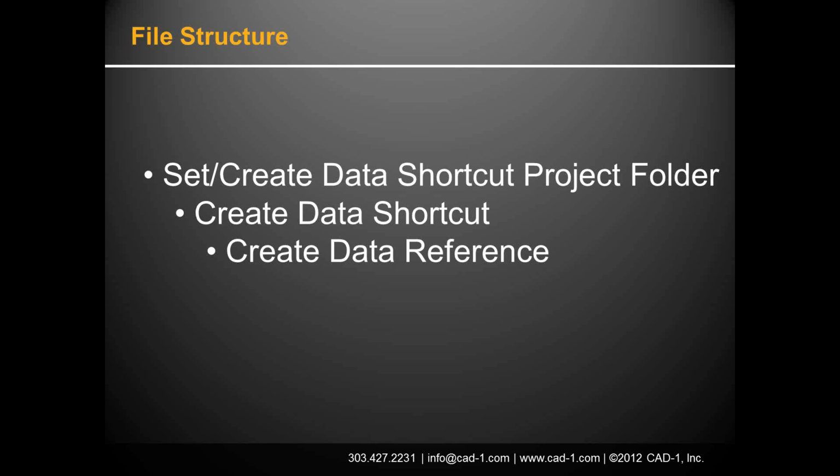And then prior to creating the data shortcut project folder, I need to set or create the working folder, and I have no idea why we need to do this, but we do. So the working folder contains the project folders. The project folder contains the shortcut, and the shortcut is used to create the reference.